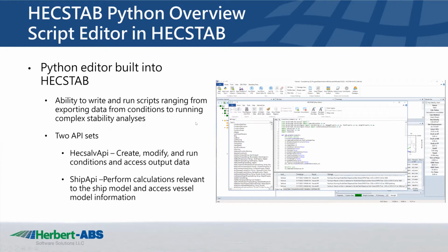If you're familiar at all with our analysis packages within HECSTAB, you'll know a lot of those are built up basically from Python scripts. So anything simple like creating damage cases from a box within the 3D graphic to a lot more of our complex ones like doing full SOLAS probabilistic damage analysis are all, for the most part, built up from Python scripts.